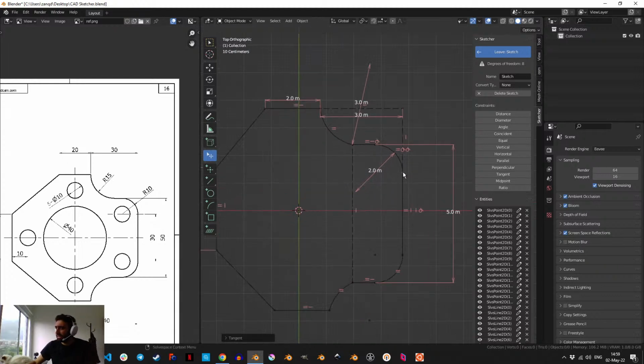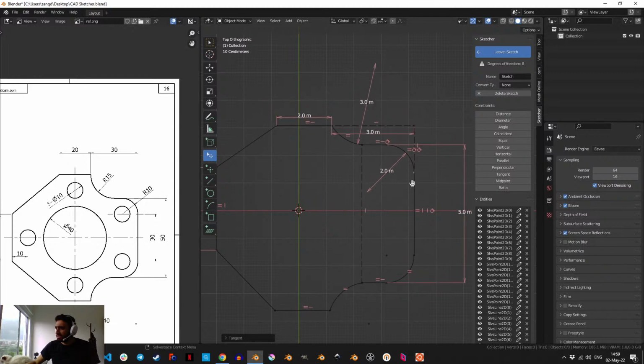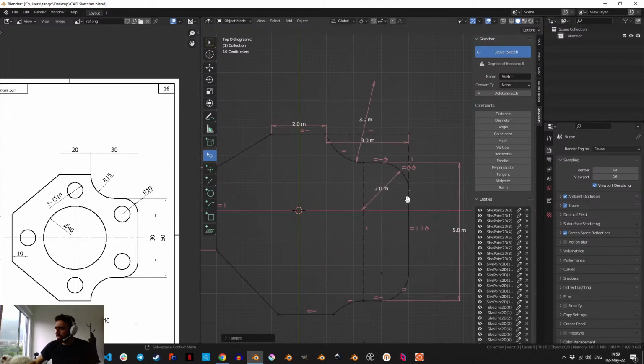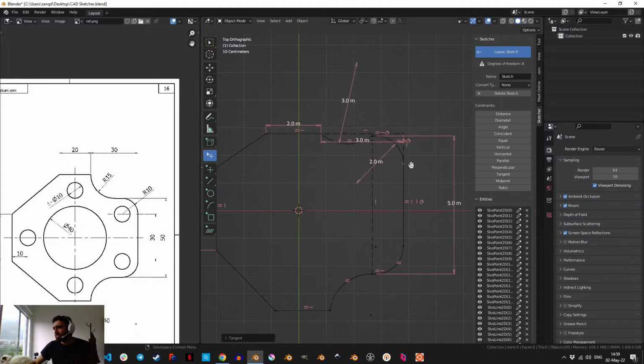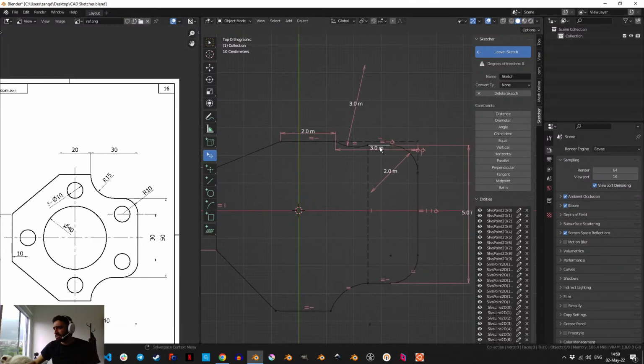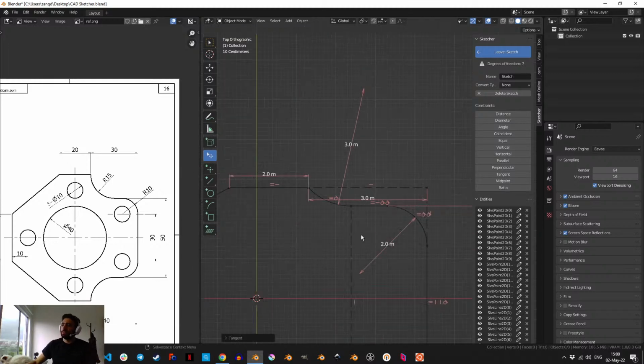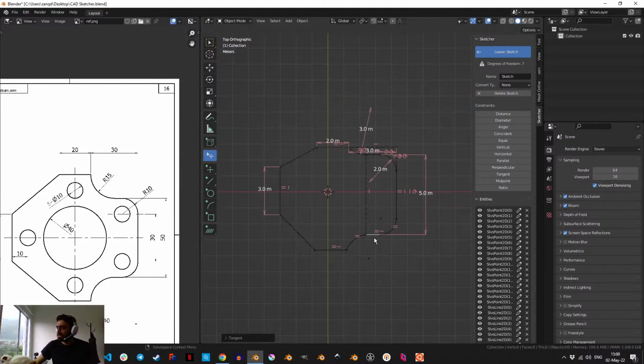Right, so I like to just move some points to see what is still unconstrained. Because you see, I should be able to add a constraint between this curve and this line segment. So I'm gonna try again, but I'm gonna save first. So tangent between this and this. Why? There you go. Now it did it. It's probably just a UI issue, I guess.